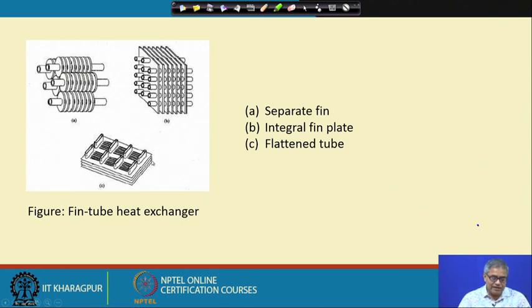Again we are going for design C. In the design C, what we can find is that these tubes have been made flat. There are several reasons why we like to make this tube flat. One reason could be that a circular body is a blob body, and when we are making it flat, we are reducing the form drag when a gas will pass through. So, this is one variation we can find here. Another variation, you see there are fin plates, but on the fin plates there is some sort of a surface modification which has been done.